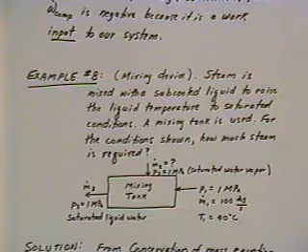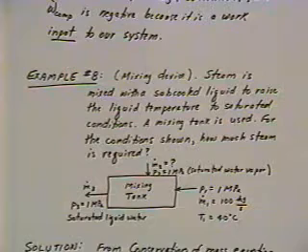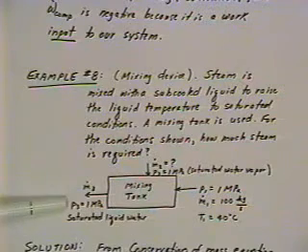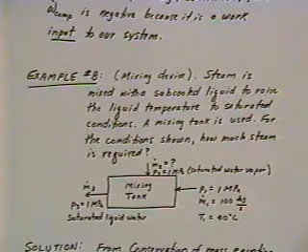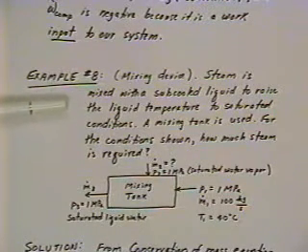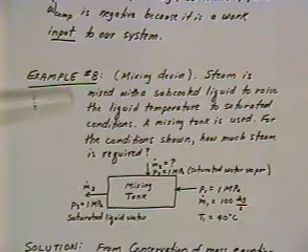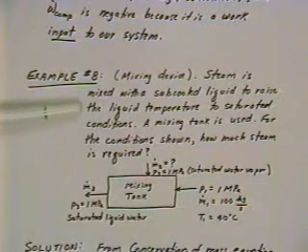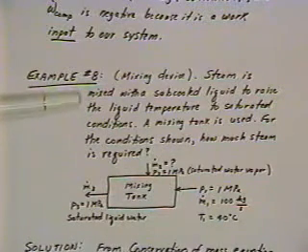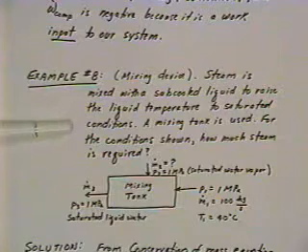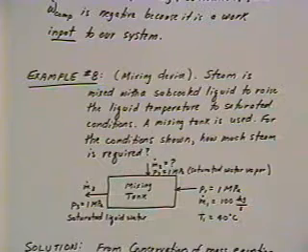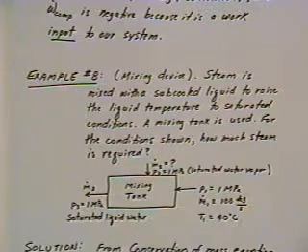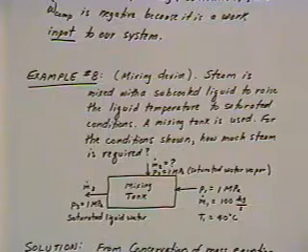We've got steam coming in one side. We've got subcooled liquid water coming in at another port, and leaving we've got saturated liquid leaving. And so what this is we've got steam that's mixed with a liquid. In this case it's going to be subcooled liquid, and we'll remind you what the definition of subcooling is in a minute. And the whole point of this is to raise the liquid temperature leaving to saturated conditions. In a power plant, for instance, you have a higher efficiency in the boiler, for instance, if the water entering the boiler is at a higher temperature.